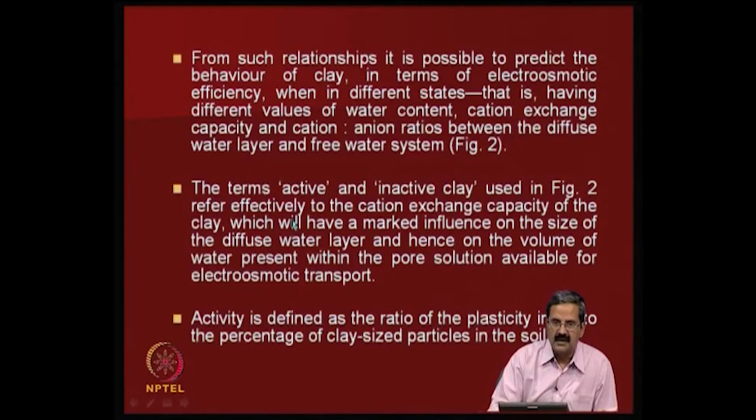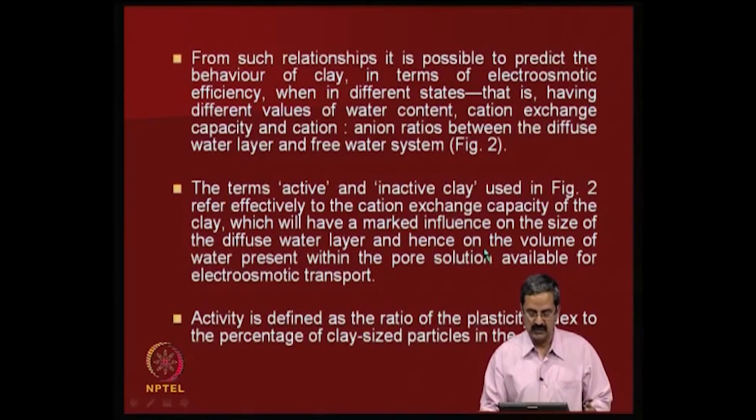There is another term that we should see: the terms active and inactive are related to the size of the diffuse double layer, and hence to the volume of water present within the pore solution available for electroosmotic transport. What it means is, if the clay is very active, how do you define the activity of the clay? Activity is defined as the ratio of the plasticity index to the percentage of clay size particles.